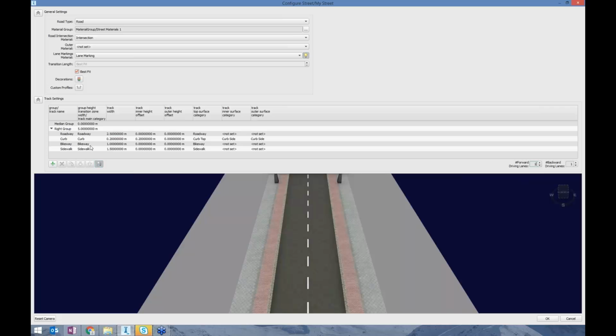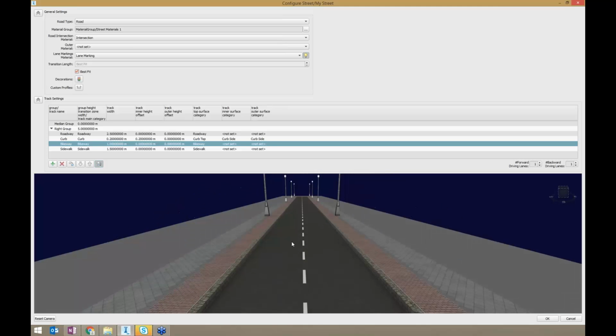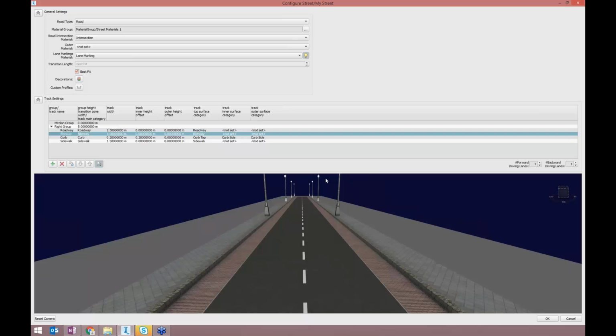So I'll have a bikeway. That's good because I need one. But I see this bikeway, in my case, is not on the pedestrian level, it's on the road level. So if you go in here, you see the curb and then the bikeway. I need it all the way around. So I press these buttons to move it up. And you see the bike lane goes down to the road level and then the curb comes.